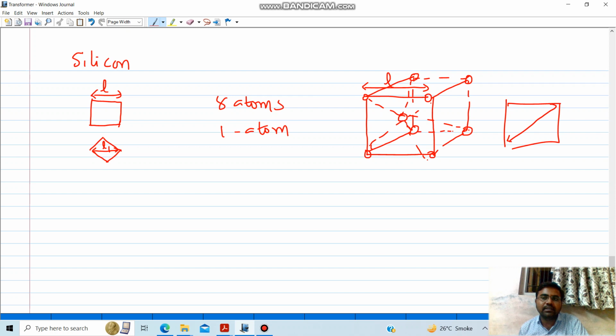If you look at this length, let's say this is a square with sides L and L, then the diagonal will be square root of 2 L. Now in the magnetic material, if the crystals are placed randomly, then the flux has to pass through this bigger length, and as you know reluctance is given as length upon mu times area. If the length of the magnetic path increases, then reluctance also increases. This is one of the drawbacks of silicon steel material.